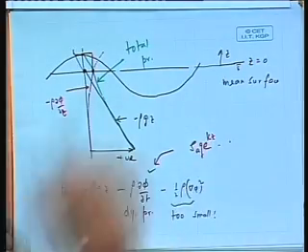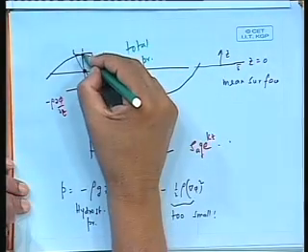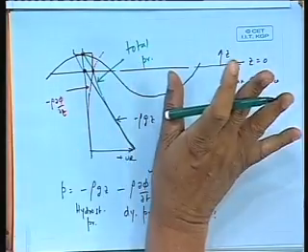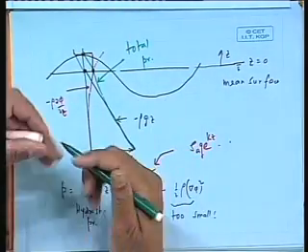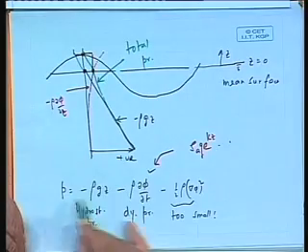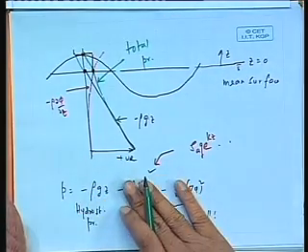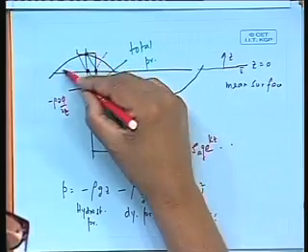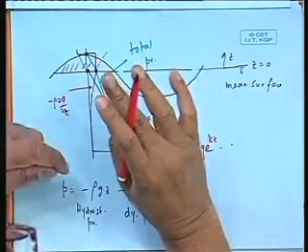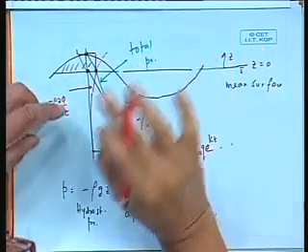pressure. And if you look at the total pressure, there is no contradiction. The total pressure is 0 here, which is how it should be. Total pressure here is equal to rho g into this height and it goes like that. Why I say that is because sometimes we will be using this formula and then you forget this formula and only use this formula under a wave. Under a wave, using hydrostatic pressure is meaningless within the crest, because if you took within this crest region hydrostatic pressure alone, then you will always end up getting a negative hydrostatic pressure, which is meaningless.